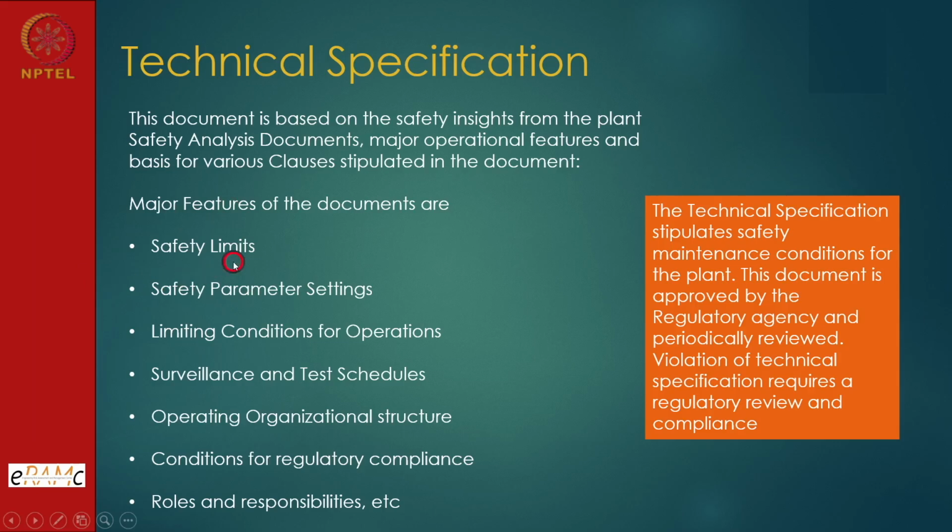So, the first part which is safety limits, the highest component of the safety, it should not be violated in any case. If it is violated, then the plant is shut down, and then the limits are reviewed by the regulators, and then finally depending on the corrective mechanisms, recommendation and oversight, testing and all, the plant can come back to operation. It does not mean the plant has gone into an accident condition. These are the preventive provisions in the plant. They should not touch the safety limits.